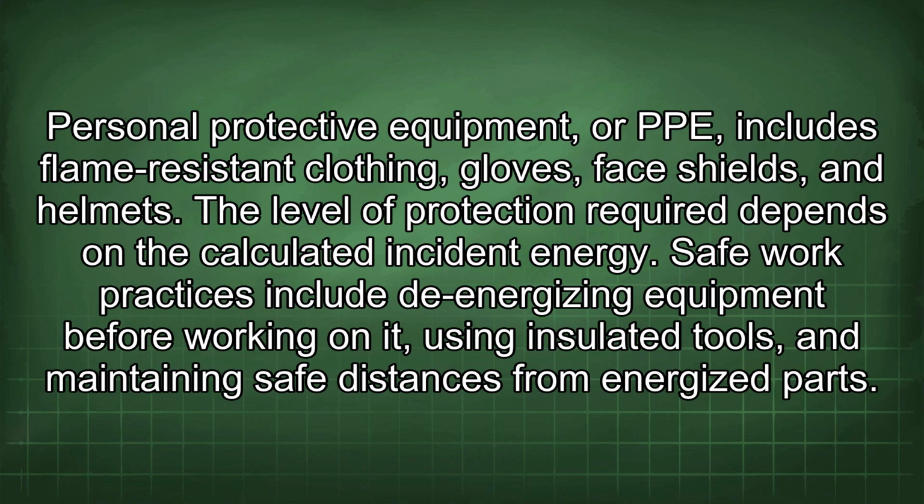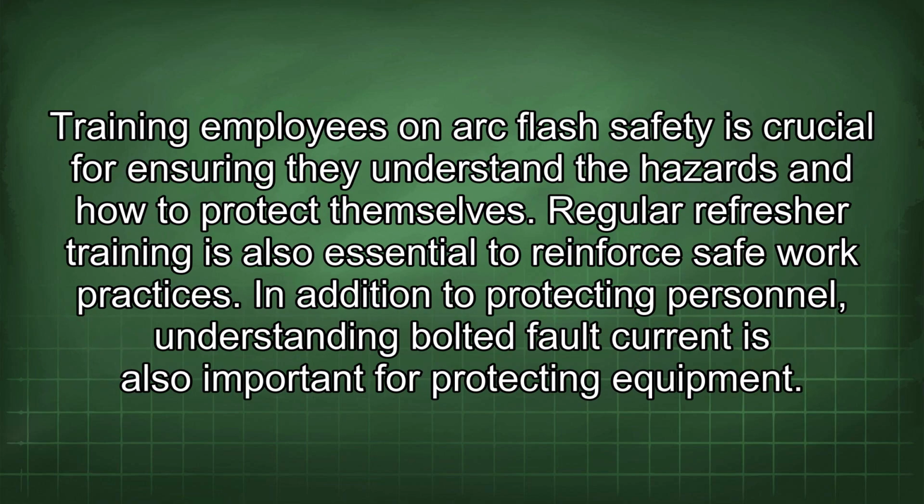The level of protection required depends on the calculated incident energy. Safe work practices include de-energizing equipment before working on it, using insulated tools, and maintaining safe distances from energized parts. Training employees on arc flash safety is crucial for ensuring they understand the hazards and how to protect themselves. Regular refresher training is also essential to reinforce safe work practices.